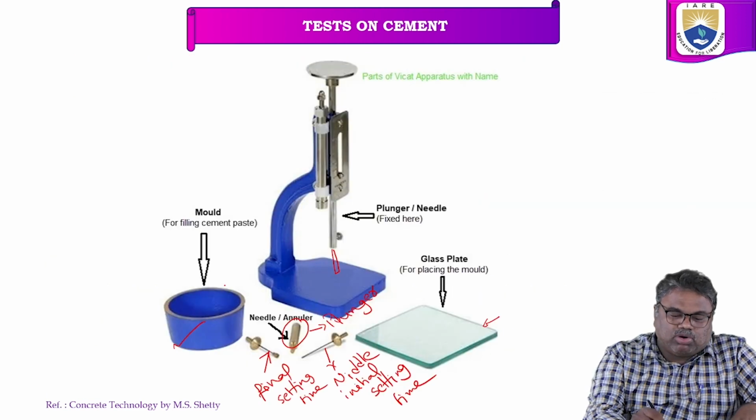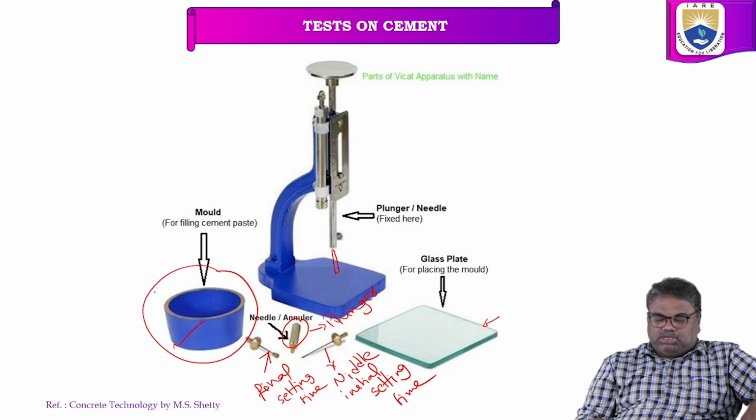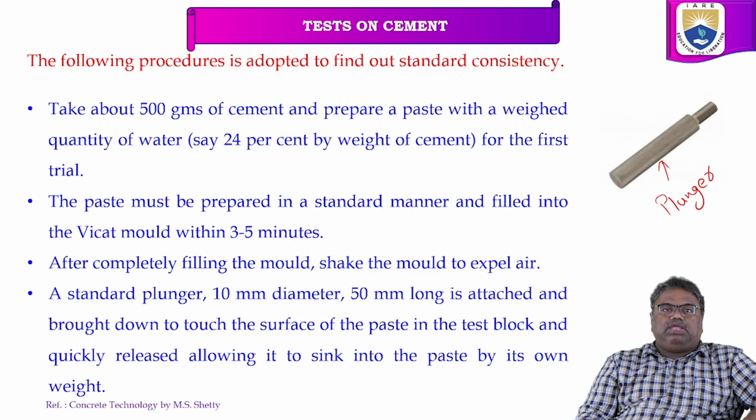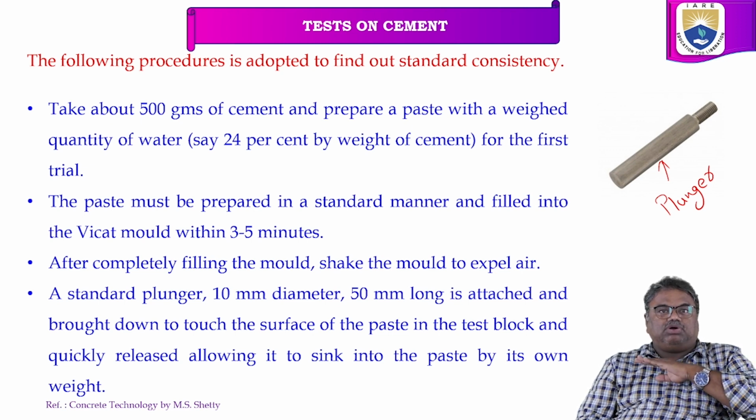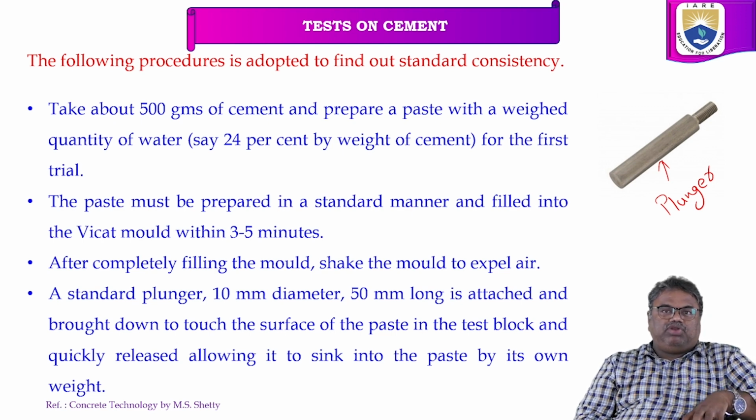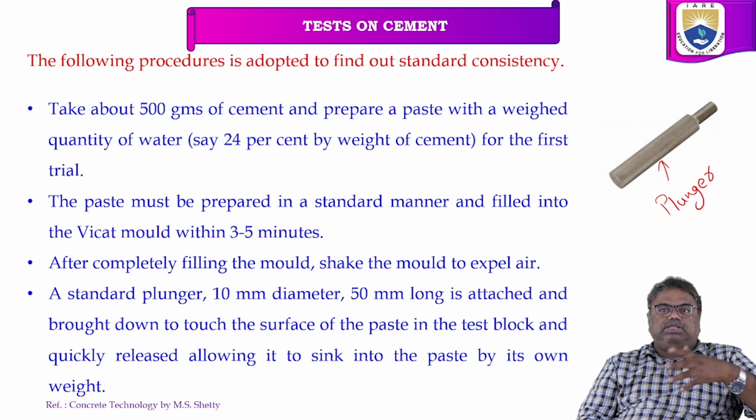So this is the Vicat mold. We have to fill this paste into the Vicat mold within 3 to 5 minutes. After completely filling the mold, shake it well to expel the air.